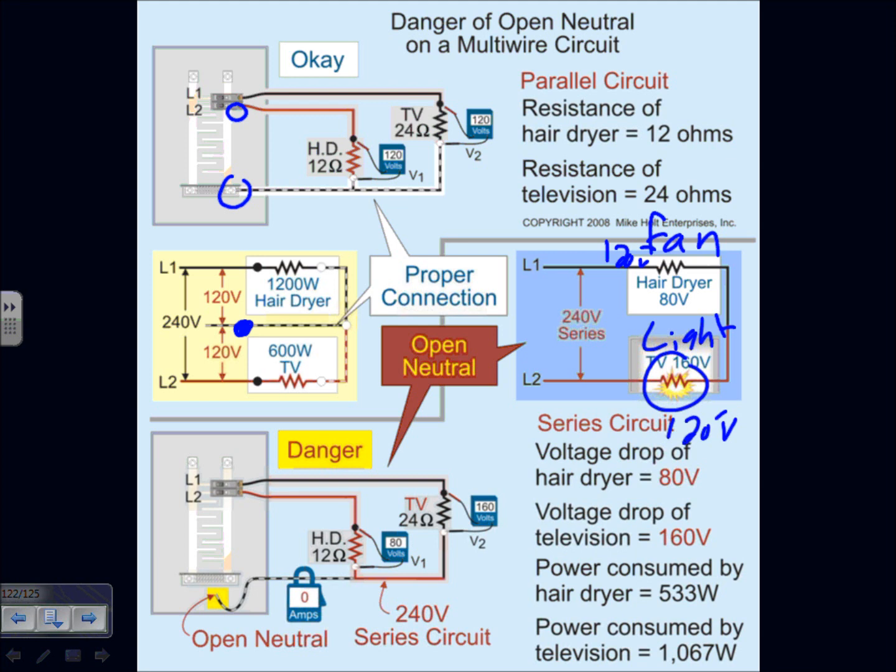Bad news. We don't put power equipment in series. Remember, we just talked about series. You put them in series and there's a big chunk of voltage across you. The biggest, fattest, highest impedance one will hug most of the voltage, which happens to be the light. And the smallest, skinniest piece of equipment will take a lower amount of voltage, so they can add up to what? The source voltage. They have to add up to the source voltage, as we all know.